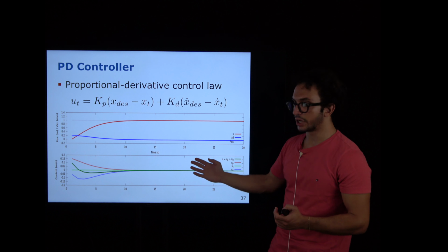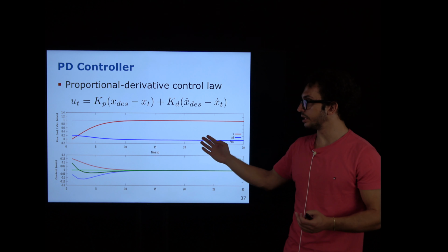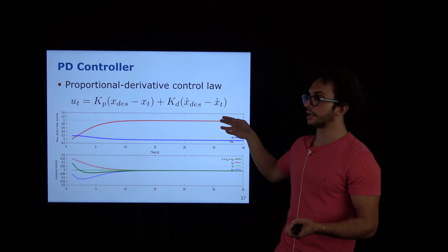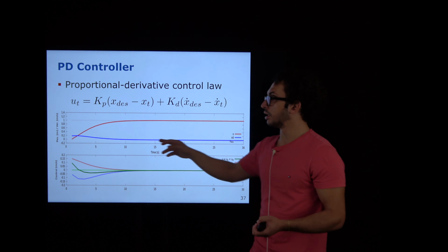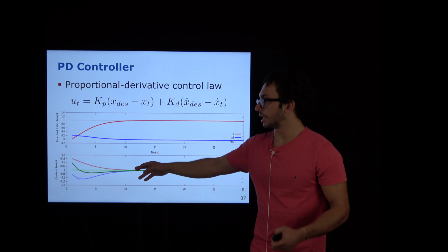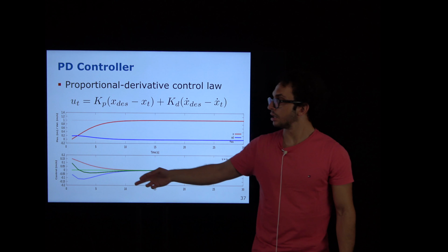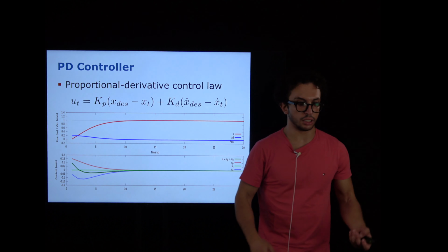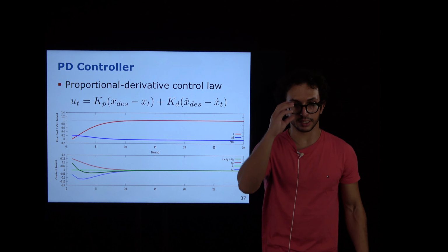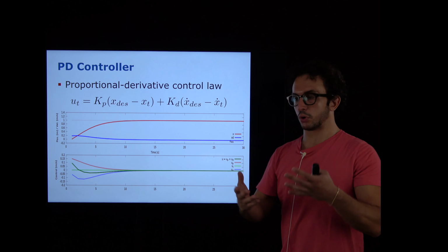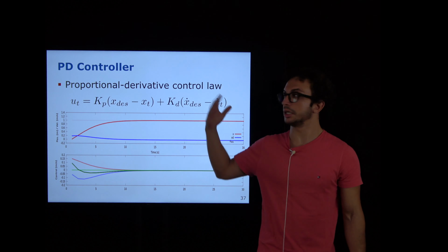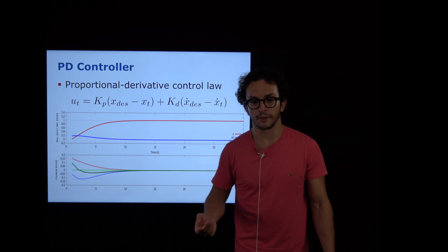This is what happens. So we have now solved the control problem. The position goes to 1 asymptotically. There's no error anymore. And the velocity eventually goes to 0. We have now terms: the red one is the proportional gain, the purple one here is the derivative gain, and the dark green one is the total control action, which is composed of the two components, while this light green, which is still at 0, is the integral part, because there's nothing happening here.